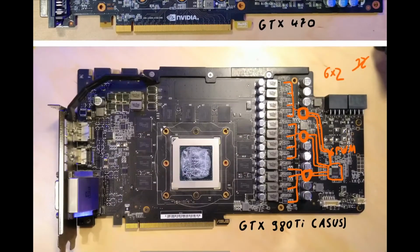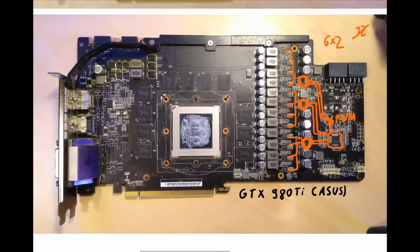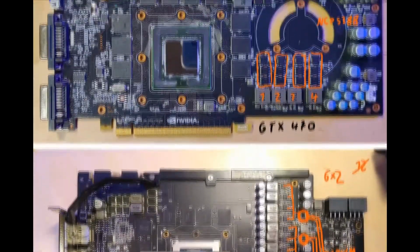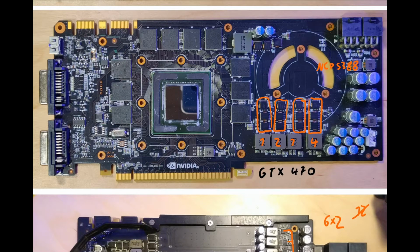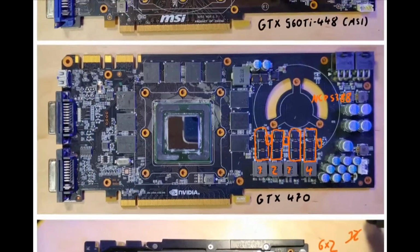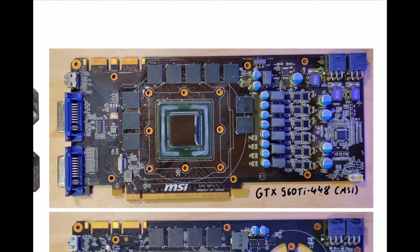And then for power stages, there's basically the same thing. It's just a little harder to find all the specifications, since it's basically a lot of things in one. Power stages also include drivers, which can also be doublers. So doublers and drivers can be the same thing. This card does not have doublers, but it has these little chips right here, which I can't find for that phase actually. Did I cover it somewhere? Yeah, there's a 4th chip somewhere in the VRM. These are the drivers for that VRM. They're not really that interesting, except for when they are doublers.